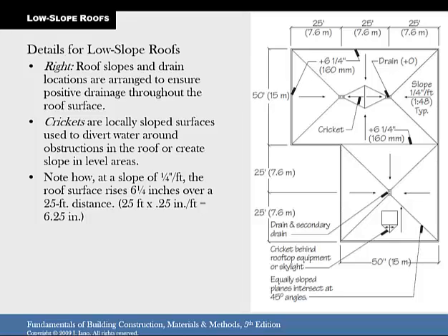So this is the low point. You got 35 feet to there. The horizontal run is 35 feet. So 35 times 1/4 inch per foot, or 0.25, is going to be 8.75. So the high point of your roof is going to be 8.75. Yeah, you're smarter than you thought.